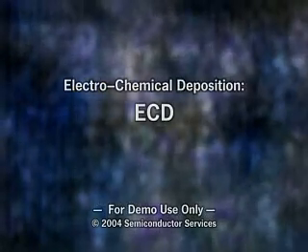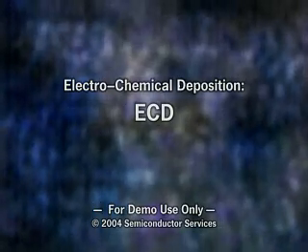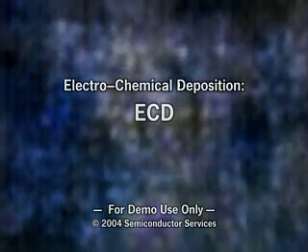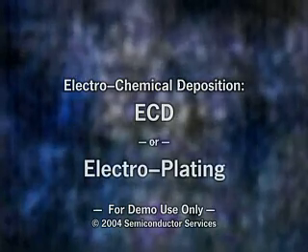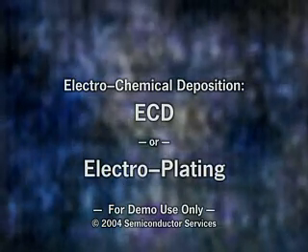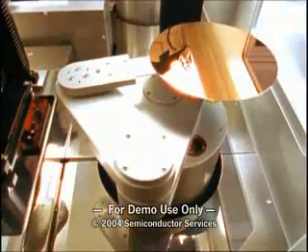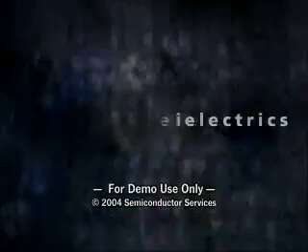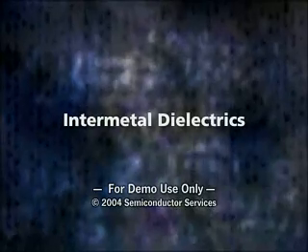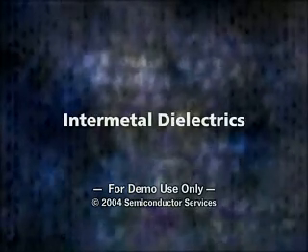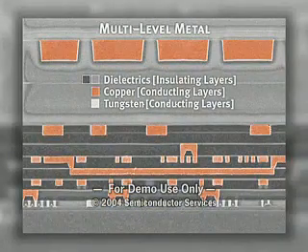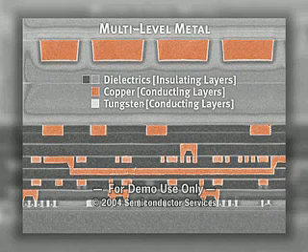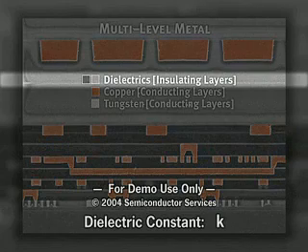Another method of depositing a metal on the wafer is electrochemical deposition, ECD, also referred to as electroplating. An important use of ECD is to deposit copper layers. An important issue in the multilevel wiring structure is the dielectric constant, called K, of the material used for the insulating layers.